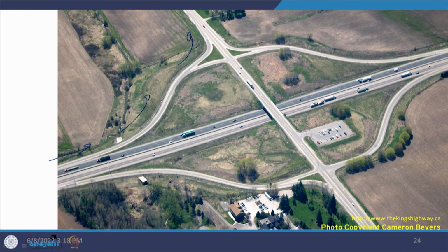So, we have this diagonal connectivity, but then the traffic which is desiring to take a right turn has to come to this location and then take a turn here. So, it is an at grade condition. The stop and go condition is going to be there at this location, and if it has come down wrongly, then there is a provision by way of which it can again go and meet the main highway. So, here also the things are happening at grade, and here also. Only one structure which has a grade separated condition is being provided at this location.